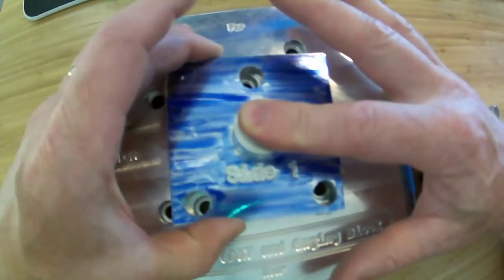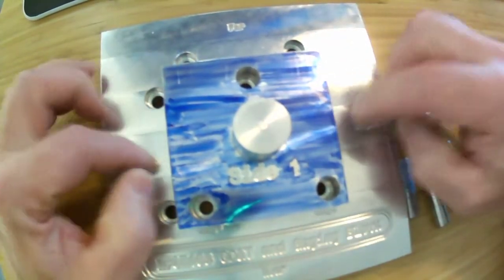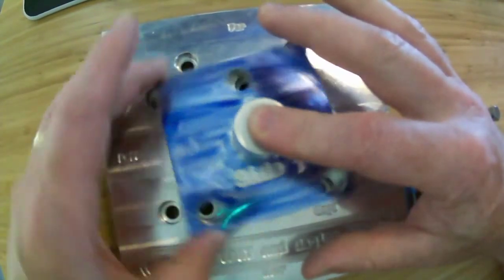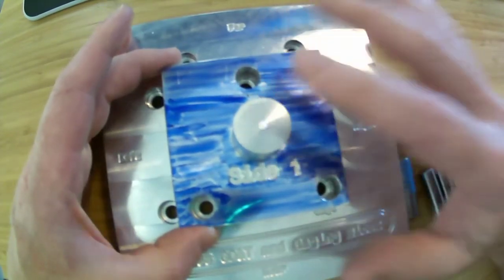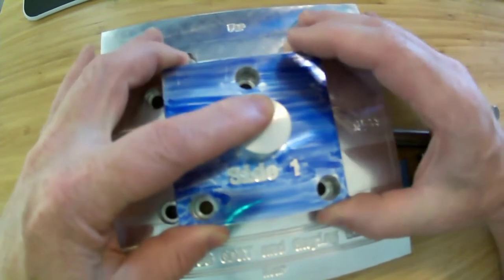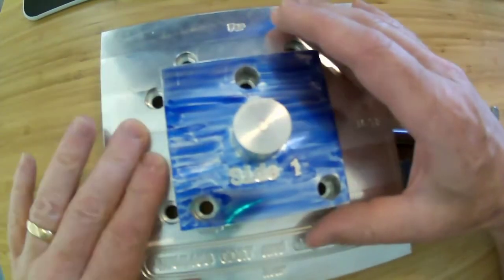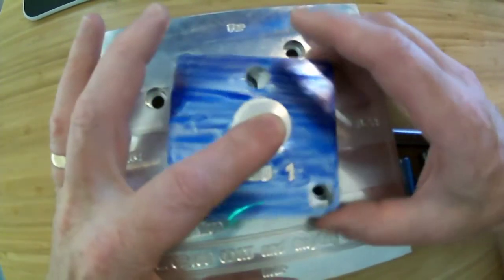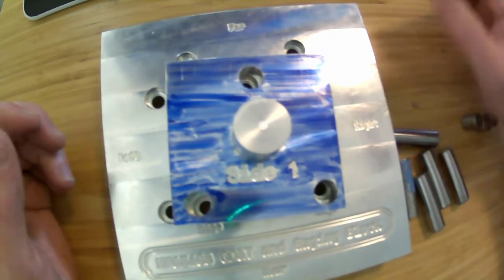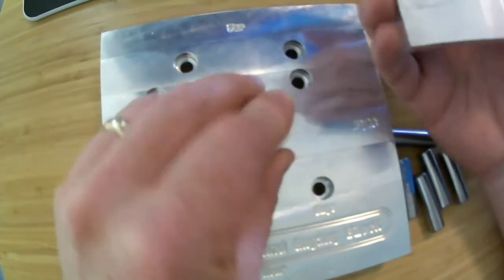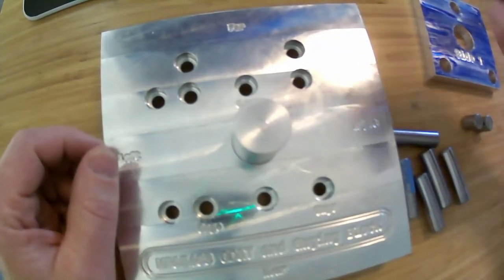So how many degrees of freedom have I eliminated here? Well, if the part is down on this surface, the only thing that I can do with it is rotate it around the locator. So I've eliminated 5 degrees of freedom. Remember, it can move up the locator, but I'm going to clamp it down against the bottom surface. And so with this plane and this cylinder, I've eliminated 5 degrees of freedom. Is it deterministic? No, not really. Because just like we talked about before, I don't really have any idea where this flat is touching this surface down here. How could I make it more deterministic?